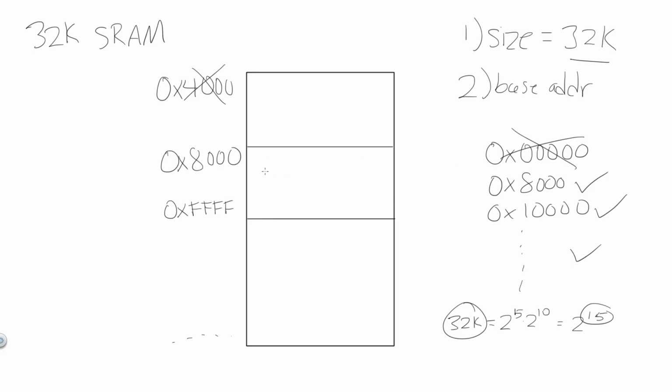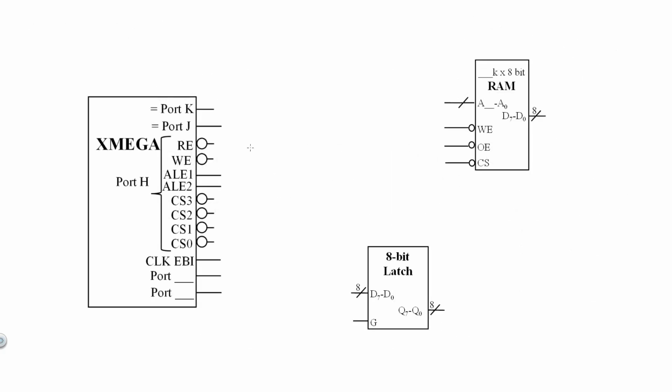Now I'm going to go ahead and label this section of the memory map corresponding to the device that I'm going to place here. I'm also going to specify which chip select that I'm going to use so that I can keep track if I have multiple devices that I'm adding. Now let's see all the physical connections that will be required to successfully interface with this SRAM.